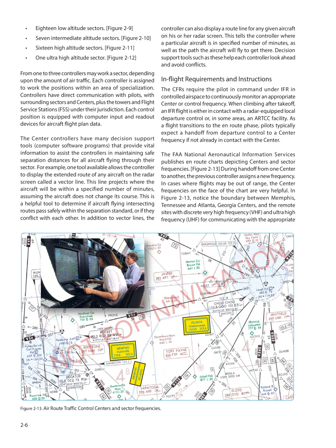Controllers have direct communication with pilots, with surrounding sectors and centers, plus the towers and flight service stations, FSS, under their jurisdiction. Each control position is equipped with computer input and readout devices for aircraft flight plan data. The center controllers have many decision support tools, computer software programs, that provide vital information to assist the controllers in maintaining safe separation distances for all aircraft flying through their sector.